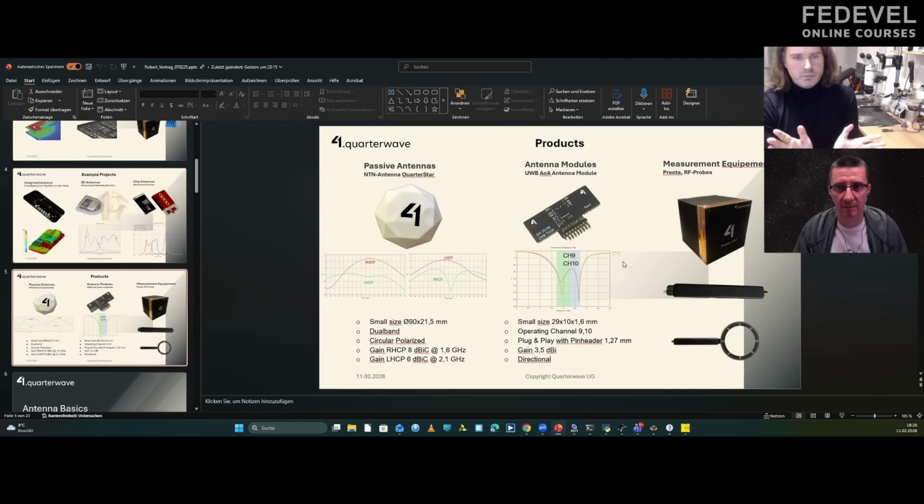It covers one hemisphere. It's a directional antenna with 2 patch antennas, because we are speaking about AOA, angle of arrival. For angle of arrival, you need 2 antennas, and we are using 2 patch antennas. This helps the customer to test things very fast, because usually you have big eval boards with big antennas, and these are not very comfortable for doing real measurements, and therefore we have developed our own module, and we are also developing our own measurement equipment, like that one with the ESP32, or like the pre-OTA box.